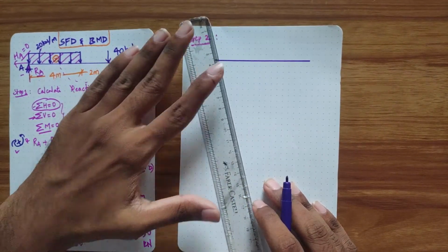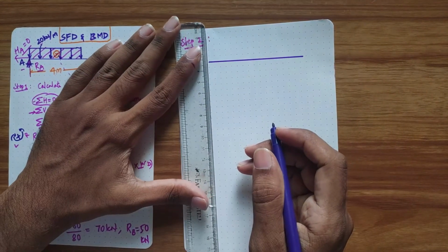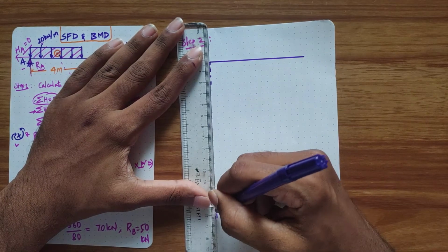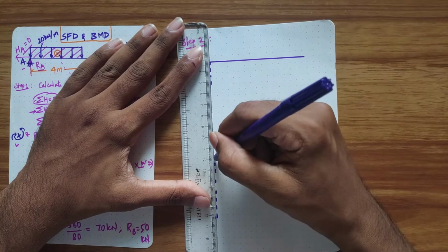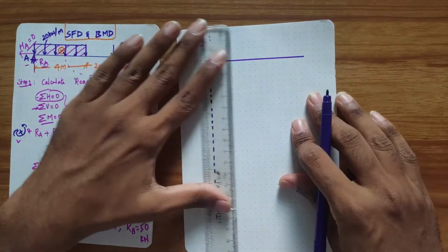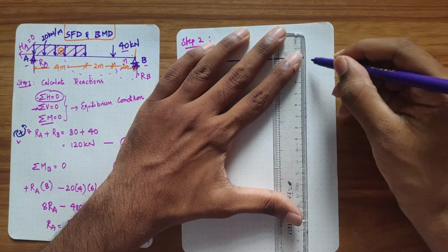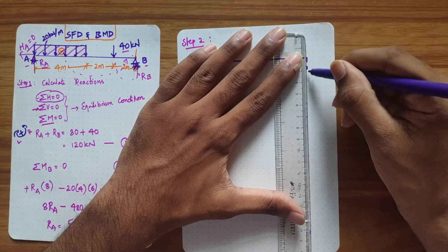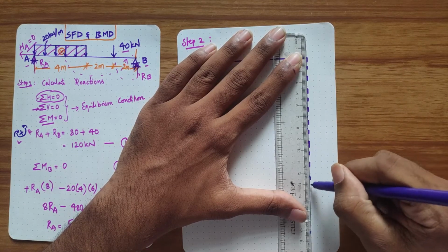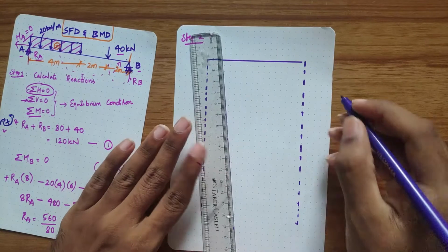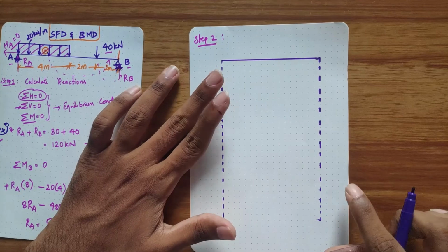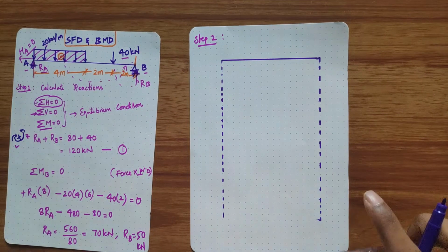Okay, the blue color which I am using indicates a given data, so that we can keep track of what's happening. So one for shear force and one for bending moment. All we need as inputs are the reaction at A and the reaction at B. We don't need anything else. We only need these 2 points. These both dotted lines will be the reference points for me to draw the shear force and bending moments, or in simple terms these represent points A and B extended downwards.